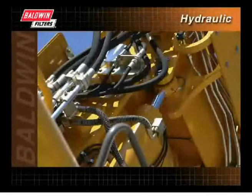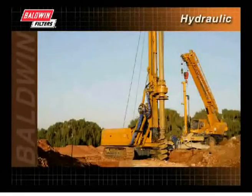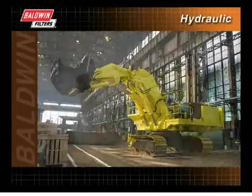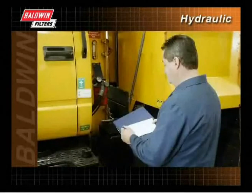As the sophistication of hydraulic systems and components has increased, so has the importance of system maintenance. Today's hydraulic systems run at high pressures and faster cycle times, causing greater system stress and increased sensitivity to contamination. Contamination can lead to system failure, resulting in major downtime and costly repairs to sensitive components. Adhering to a strict maintenance schedule will help to ensure that your filter is ready to capture damaging contaminants before they reach sensitive system components.